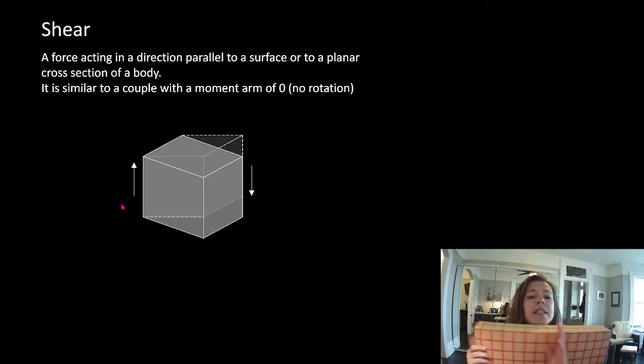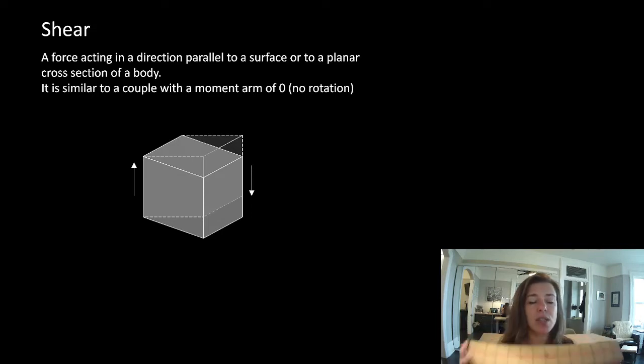Shear is this tendency for the two planes to slip past each other. As we widen that concept of the plane, it starts to look like it's skewing. But we're acknowledging that there's really a plane right here, and a plane right here, and a plane right here, and a plane right here, and a plane right here. And that amalgamation of all these planes is when people really start to try to talk about integrals and derivation. But again, we're not going to talk about it that way. But imagine that you've got an infinite amount of planes slipping past each other, and we're talking about it as a bit of a gap between those now.